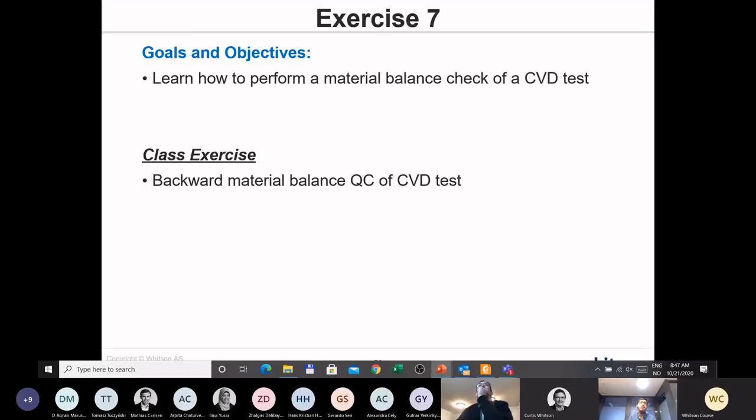If you just do a CCE experiment, as Curtis is saying, measuring for example liquid dropout or the oil shrinkage, the liquid saturations, for those compositions you already have data that is an indirect measure of the K values with varying composition, pressure, and temperature.